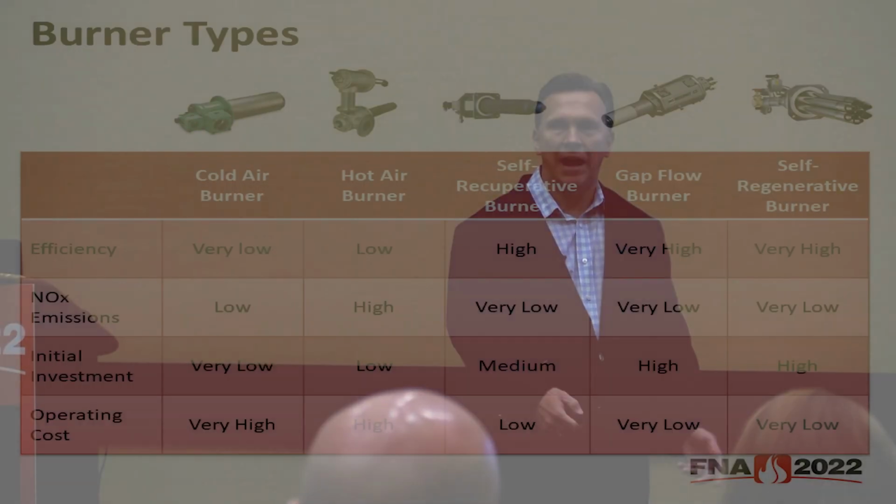So hot exhaust gases travel over the outside of the heat exchanger as they exit the furnace. Cold air flows over the inside surface, absorbs that heat, makes its way to the combustion chamber, and mixes with the fuel, forming a high velocity flame. And these burners are typically pulse fired, so on-off control, or in some cases high-low.